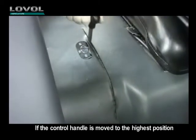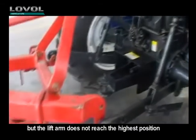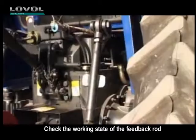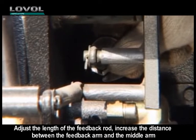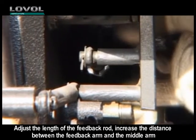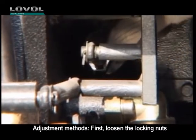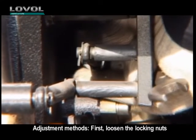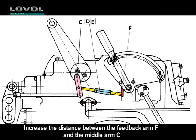If the control handle is moved to the highest position, but the lift arm does not reach the highest position, check the working state of the feedback rod. Adjust the length of the feedback rod. Increase the distance between the feedback arm and the middle arm. Adjustment methods. First, loosen the locking nuts. Adjust the adjustment screw barrel. Increase the distance between the feedback arm F and the middle arm C.